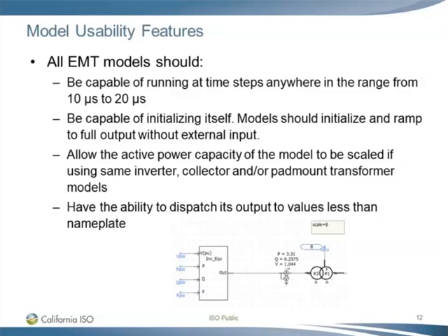Models should initialize and ramp to full output without external input from the user. The model should also allow the active power capability of the model to be scaled if using the same inverter, collector, and/or pad mount transformer models. The image below shows a screenshot of an inverter which is being scaled using a pad mount transformer component. So it's being scaled by 8.